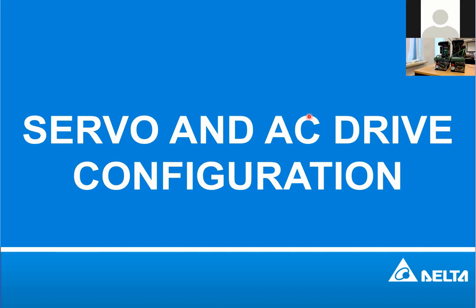We could use that function to quickly disable the inverter in case of emergency. This MI3 is connected and shorted, so the function is enabled. If it's opened, then this inverter should stop for emergency purposes.